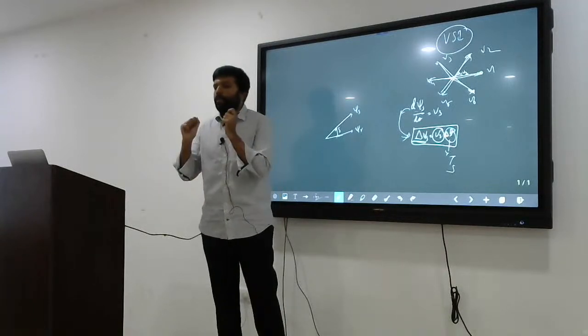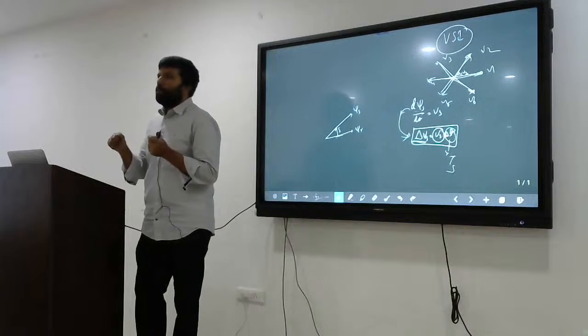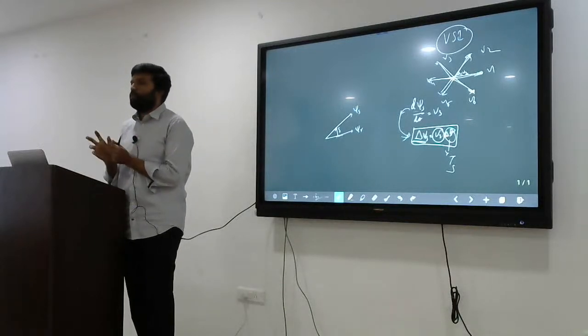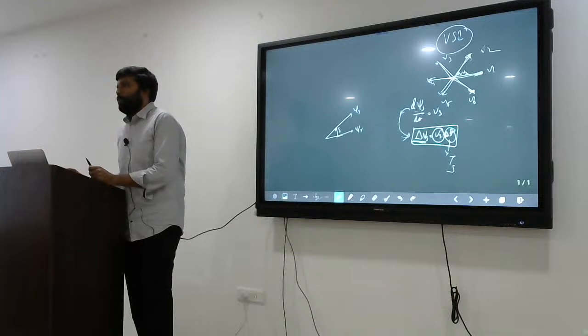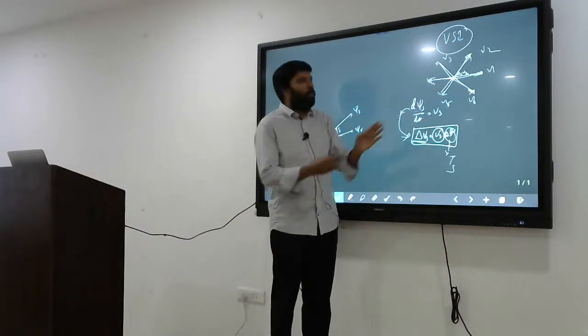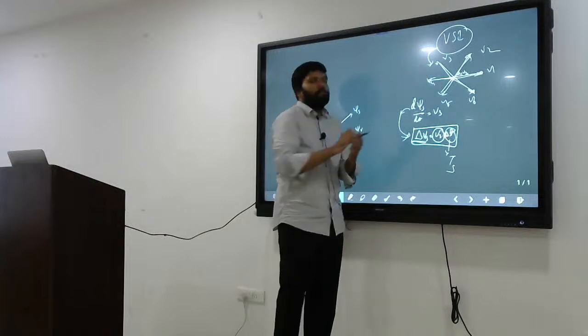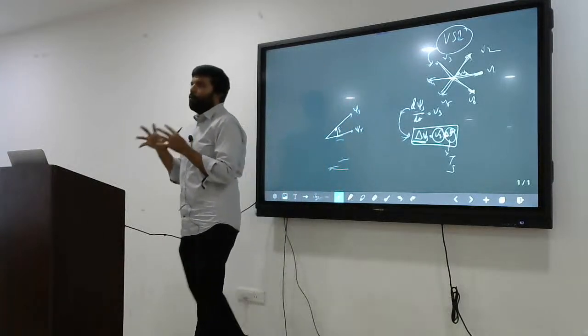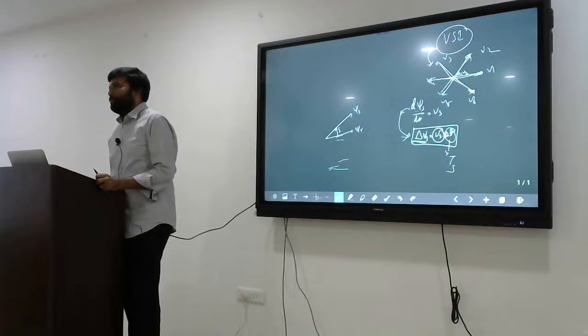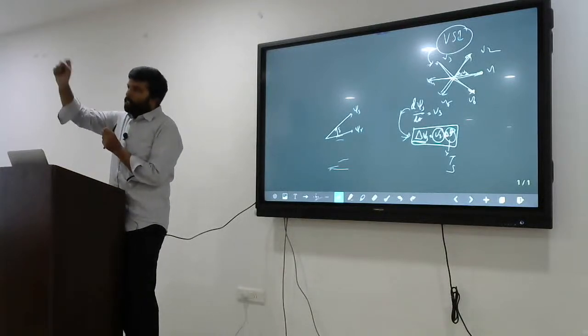But once you pick the 3-phase voltage source inverter, its characteristics will not change. This is the behavior. This is the expected output of the voltage source inverter. The output is only 6 active voltage vectors. Understood? 6 voltage vectors you will get.